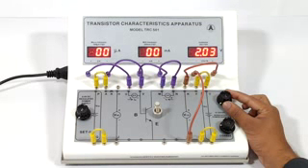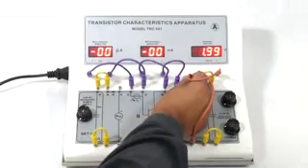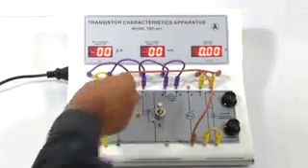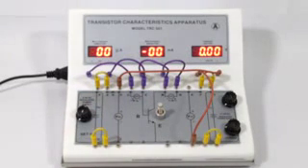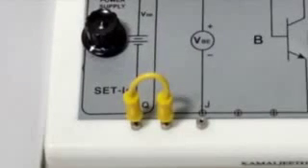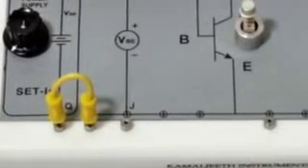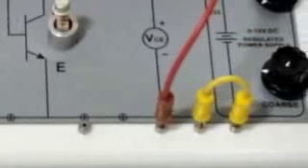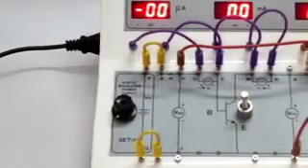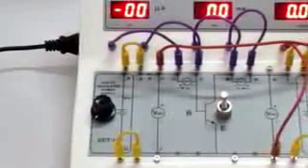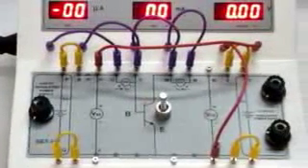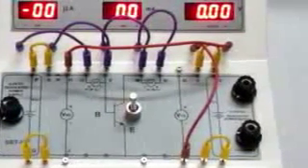Number 6. The positive lead connecting the voltmeter to the circuit in the output side is disconnected at the circuit end, and then connect the same lead to the positive point in the input side. Since all the lower terminals are interconnected in the negative side, no need to change the negative terminal connections. The voltmeter measures VBE. These are the input characteristic connections. After completing the connections, the setup looks like this.